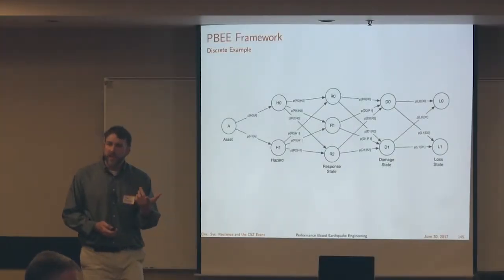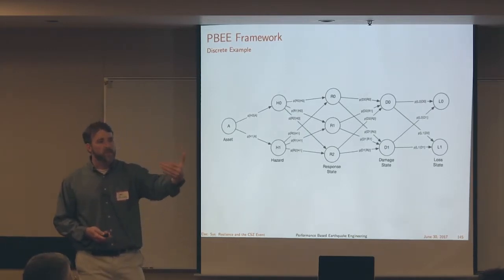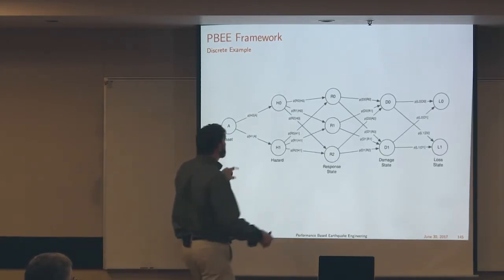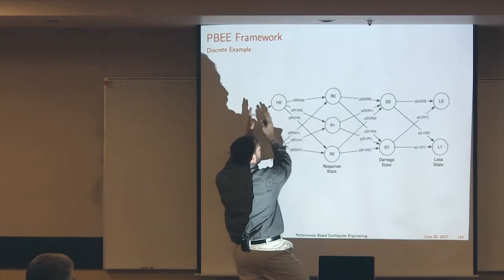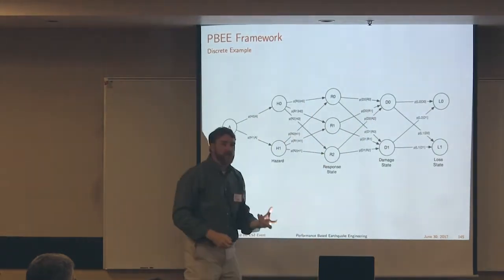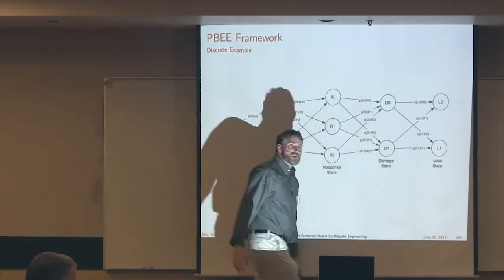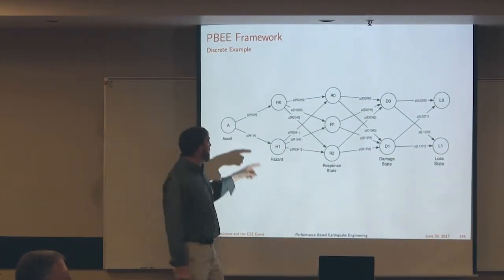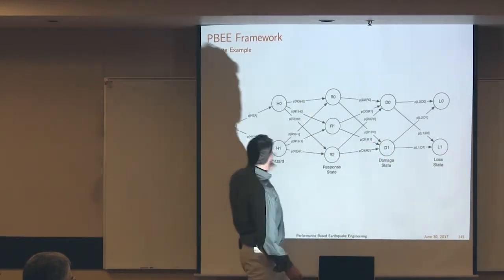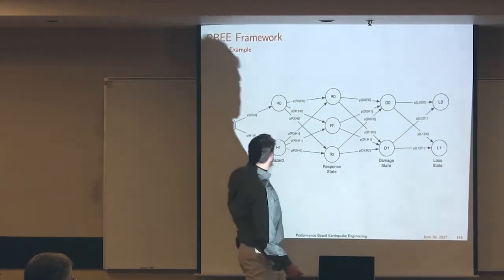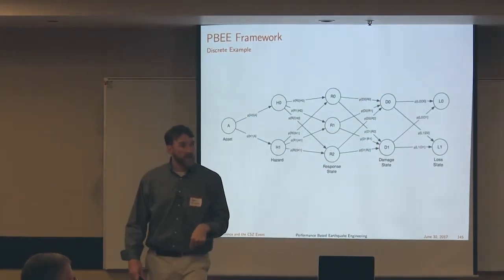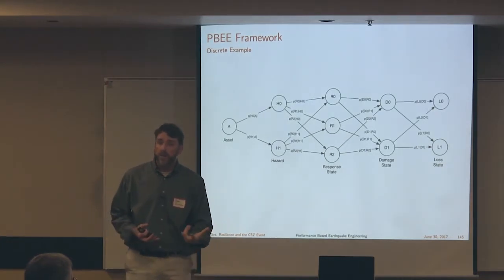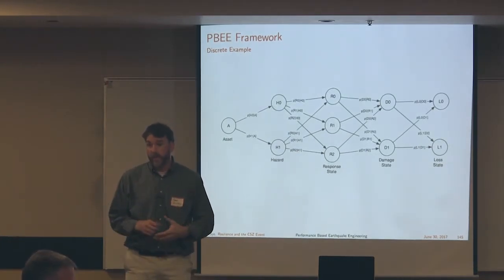But does that kind of make sense as to what you're looking at there? You're looking at a bunch of different states and the probabilities that you can move between those states. However, when we set this up, what that allows us to do is, remember, we can do some simple linear algebra to account for all of these probabilities. Because really, here's the question: what's the probability that my substation is completely lost? I have to account for this path, this path, and this path. There are many different paths through the network that get to L1, and I have to account for all of those. That's what we're going to show, how the method works. It just ends up being multiplying matrices. That's all you have to do. Does it make sense so far? Okay.